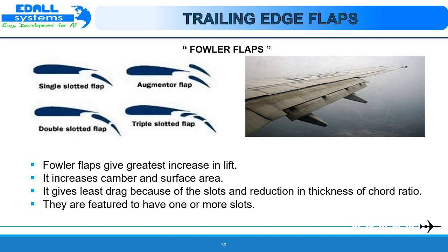Fowler flaps always feature one or more slots. It increases camber and surface area. It gives less drag because of the slots and reduction in thickness to chord ratio.